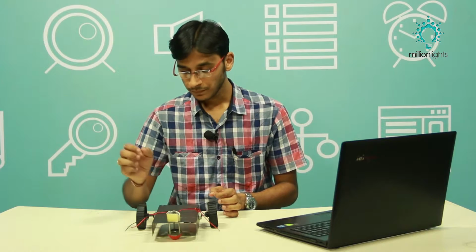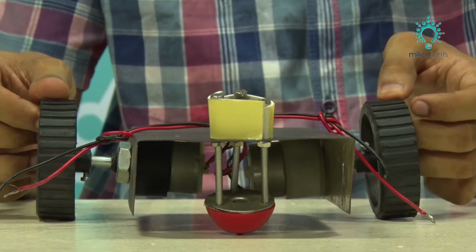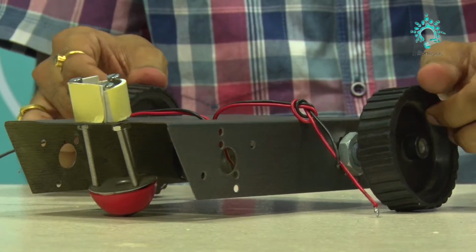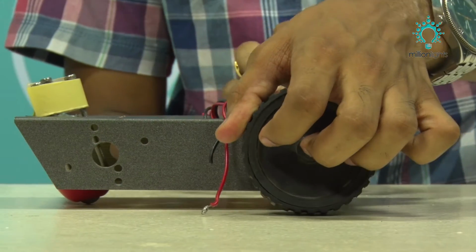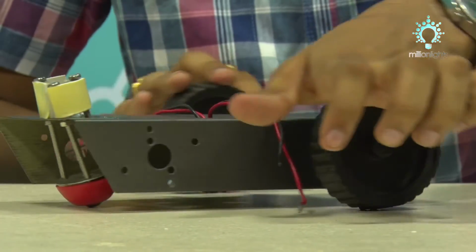Now if you want to do it in a more effective way, or if you want to take less space to rotate, or you want to rotate it quickly, then we can use a technique that is called a hard right turn. In a hard right turn, the right hand side motor is not stopped, it is told to move backwards. It moves backwards and the left hand side motor moves forward. So in less space and less time, the robot turns. It is quite simple. Once again I'll show you. That's it. In very little time and very little space, it can move on the right hand side.